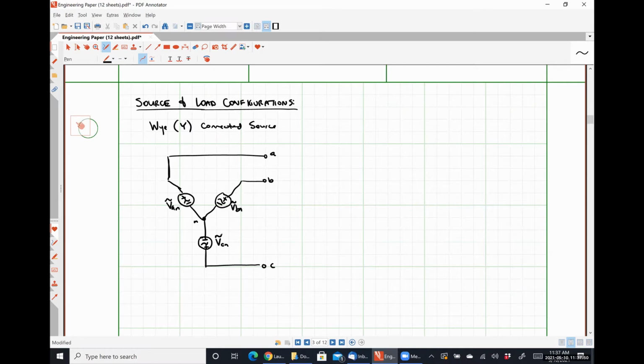It is 3 voltage sources. They are all 120 degrees out of phase with each other. They share a common neutral point, which is that neutral conductor there in the center. But it is A, a pain in the butt to draw, and B, I feel confusing. So I prefer an alternative drawing like the one I did before. So my personal preference, you do not in any way, shape, or form have to follow this.